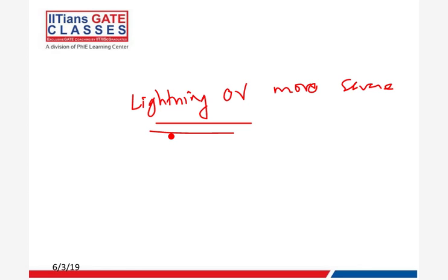We can also try alternate methods of protection against lightning over voltages, but if we go through insulation for lightning over voltages, the cost is going to be extremely high, right? So what we do is that we tend to plan for internal over voltages, right?